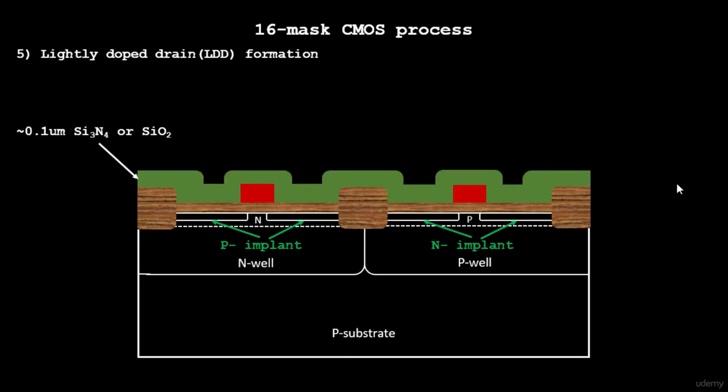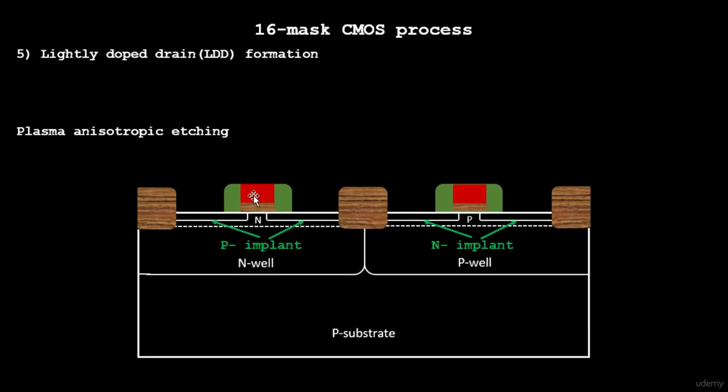You remove the extra resist that is present over here because of the UV light exposure. Now this mask can be removed, and the remaining areas of the polysilicon, the areas which are outside the photoresist, can be etched away. In that way you get your polysilicon gate. And now the final step is to remove the resist which is present over here, and this is what you get as a gate. Okay, so this complete procedure is a completely controlled procedure.